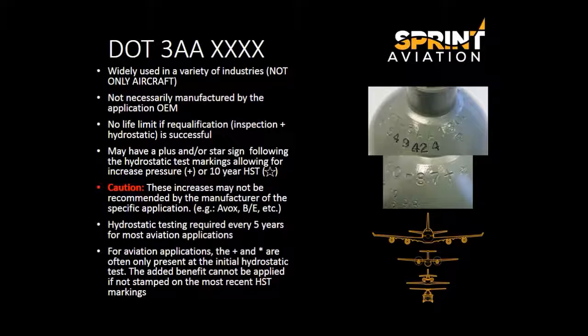DOT3AA cylinders are widely used in a variety of industries, and they're not limited to aircraft. They're not manufactured by the application OEM such as Avox or Zodiac, but by specialized cylinder manufacturers. They do not have a life limit, providing they successfully pass their hydrostatic test and accompanying visual inspection. You may see a plus and a star stamp beside a hydrostatic mark. This allows for increased pressure or a 10-year hydrostatic interval under certain usage of the cylinder.